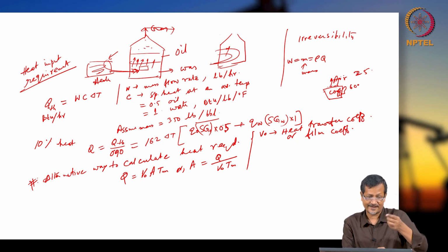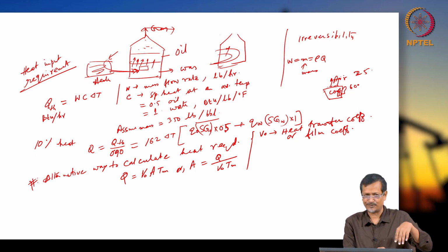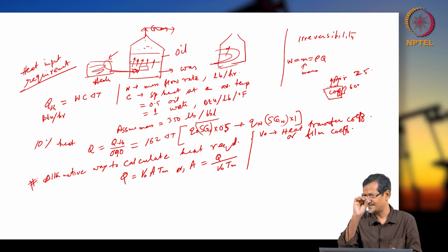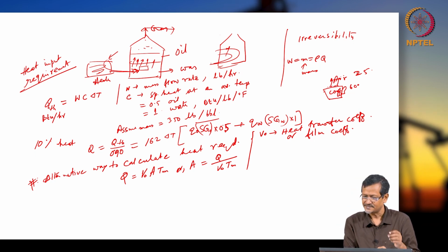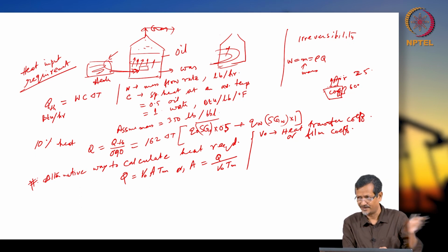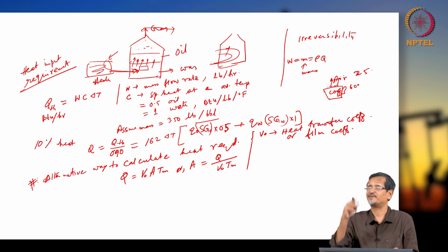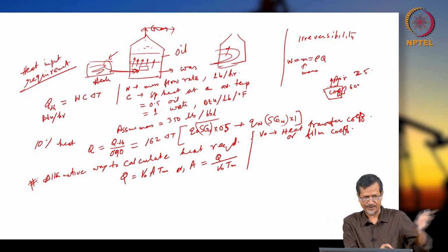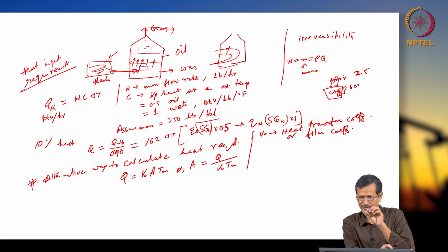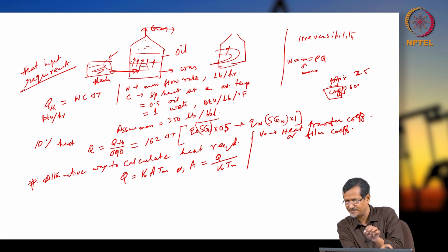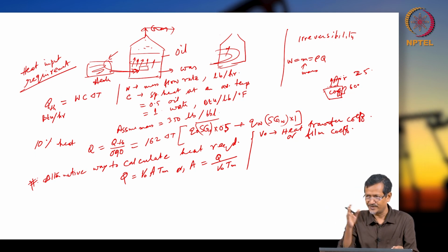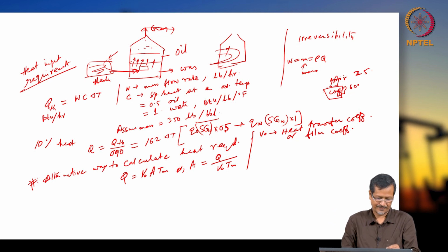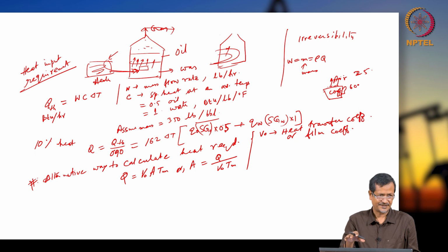Buoyancy is like the particle settlement formula you have calculated. Smaller particles move up slowly because of viscosity and density difference. Now if you blow air with a hand fan or ceiling fan or anything, the particles heated up move up quickly, fresh low temperature particles come, get heated, and move quickly. So you are removing the hot particles quickly, and the cooling rate will be very high. So the H value will be changing, and again the surface area.